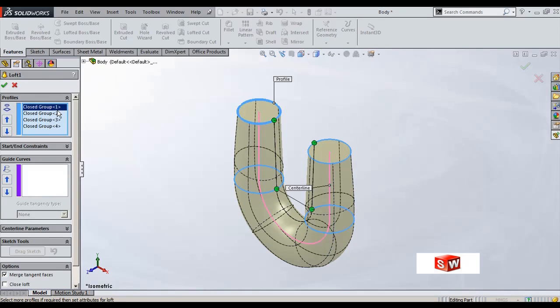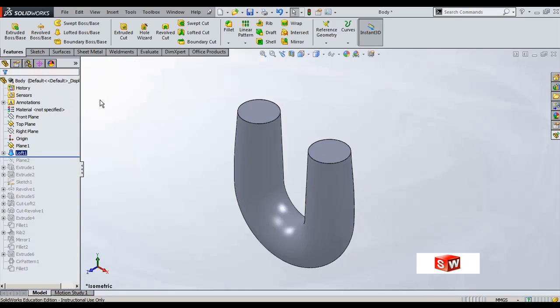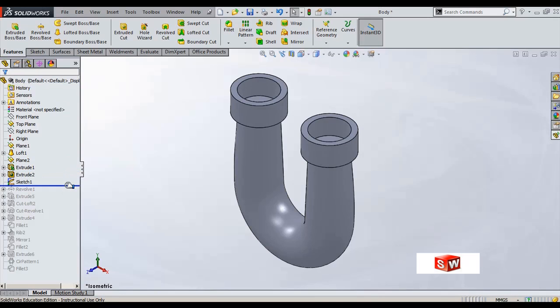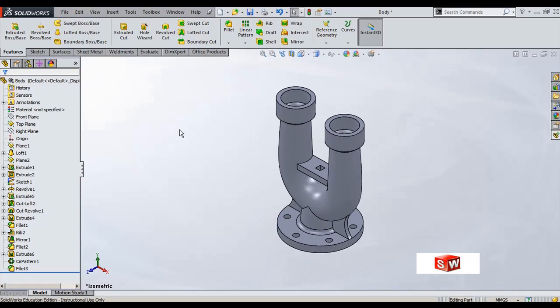the first circle, second circle, third, fourth. Using different datum planes we created these, and using the centerline parameter we joined them, and ultimately we are able to create this loft geometry. One by one we start creating this, and you can see the end result, how an entire body is created. So this will give you a clear idea about the assembly procedure for the ram bottom safety wall. Now next we are going to see the machine vice assembly.